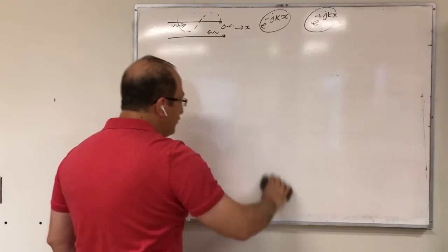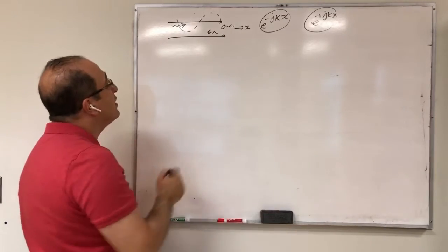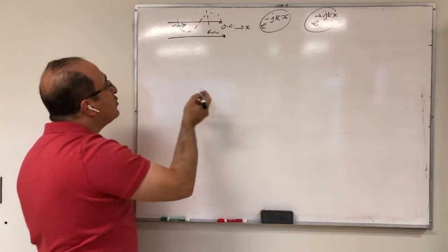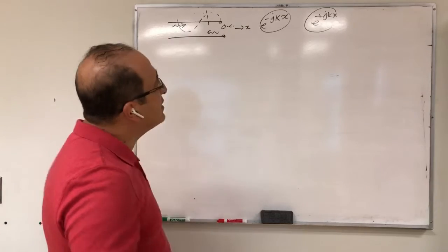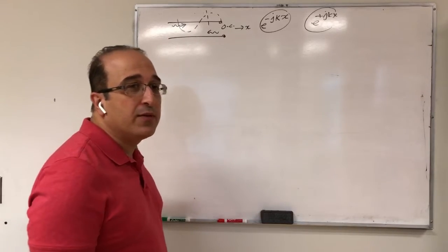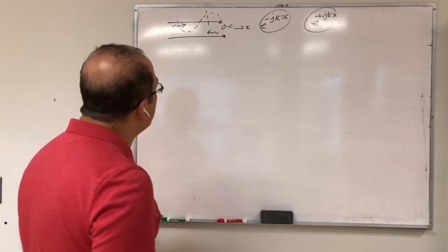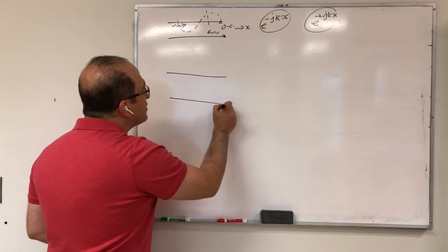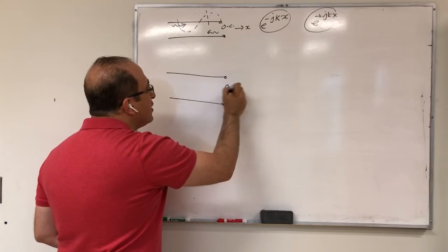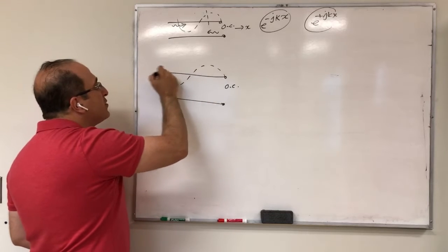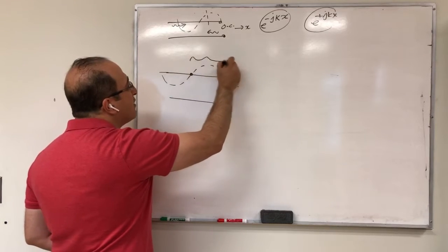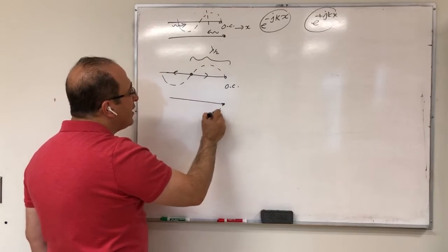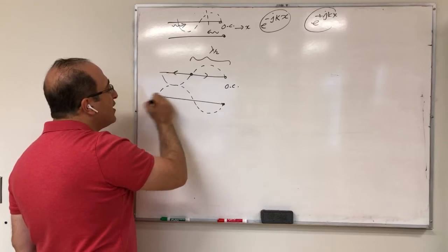Now, if you start bending this at arbitrary lengths, let's say at this length, then you're going to have essentially this sinusoidal current distribution on the dipole antenna. For example, let's assume I have this open-ended transmission line, and this is my current distribution, and of course this is half a wavelength. Now, this would be the other current that I have.